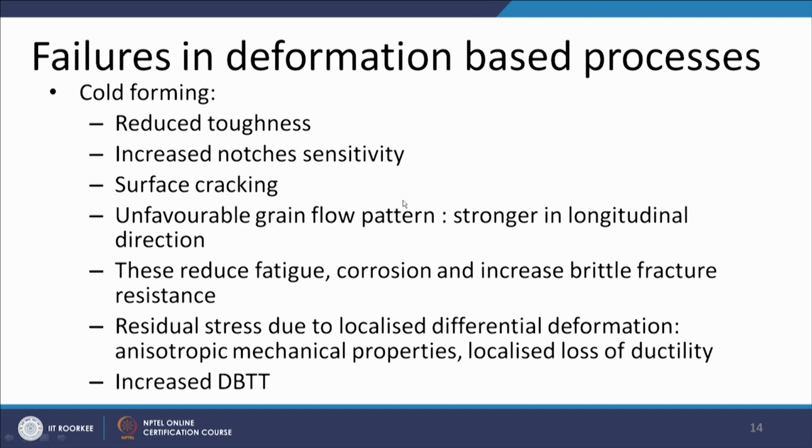cracking. Unfavorable grain flow pattern, because the metal is stronger in the longitudinal direction as compared to the transverse direction, and so it is always preferred that the loading is in the direction of the grain flow, or in the longitudinal direction. These factors in combination reduce the fatigue strength, reduce the corrosion resistance, and increase the tendency for brittle fracture.